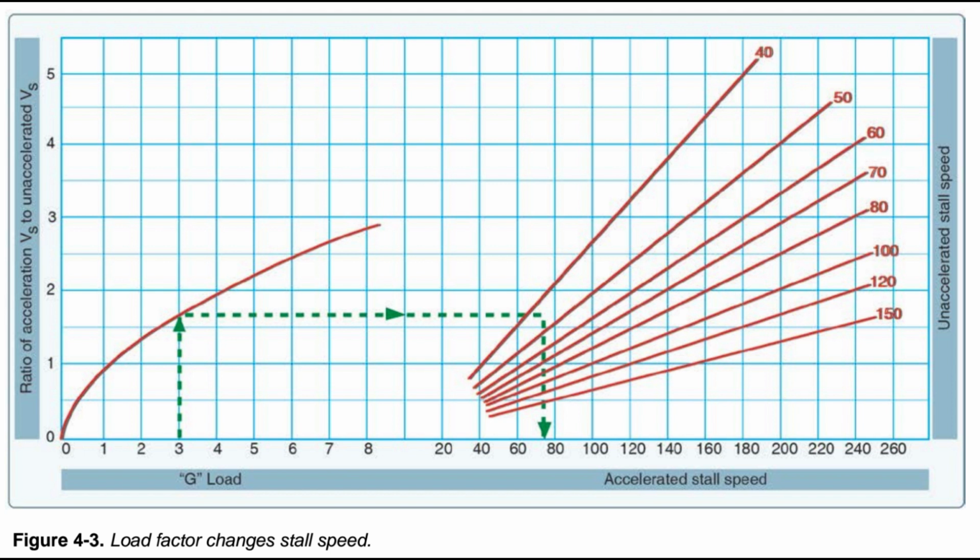For example, the most important performance deficiencies of an overloaded aircraft are: 1. Higher takeoff speed. 2. Longer takeoff run. 3. Reduced rate and angle of climb. 4. Lower maximum altitude. 5. Shorter range. 6. Reduced cruising speed. 7. Reduced maneuverability. 8. Higher stalling speed. 9. Higher approach and landing speed.